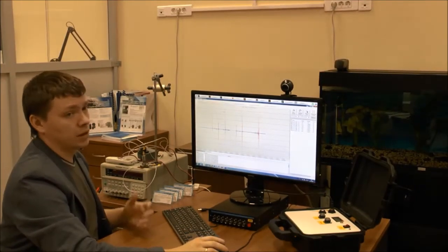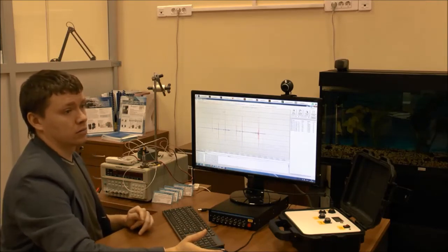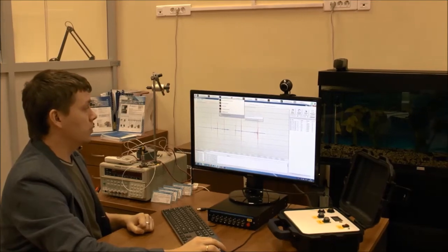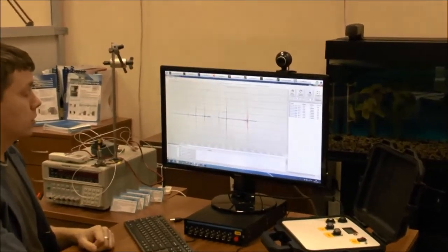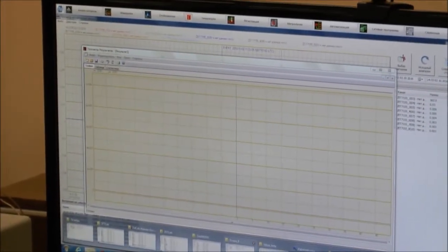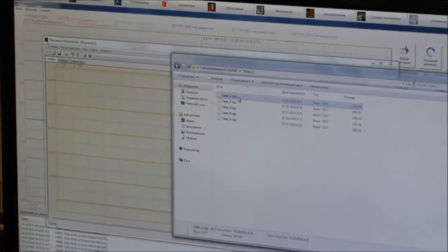Before doing that, it is recommended to use SEGY-file to review impacts data. For that, one can use ZETLAB Results View software. So we can drag the saved file, for instance, impact1, to the program window. The program shows impact diagram.